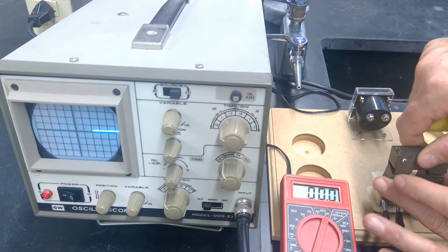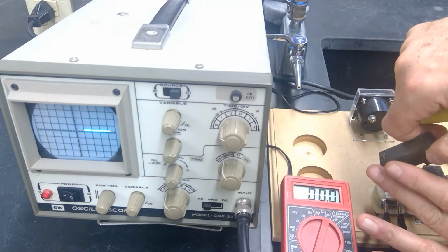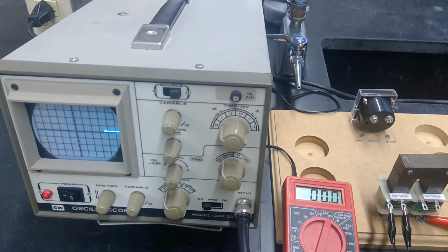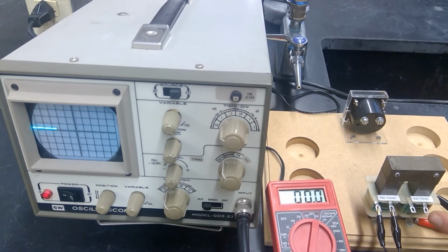So maybe stop the video for a second and think, and you may or may not need to take out a pencil and calculate what we think the voltage would be once we have changed the transformer's secondary winding from 750 to 900. So now we have a ratio of 900 to 450. Why don't you pause this video for a second and see if you can figure out what the expected voltage should be.